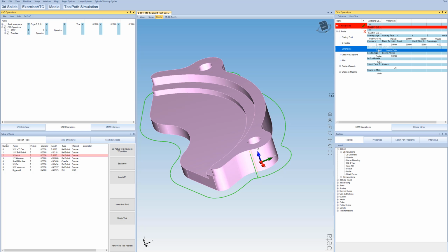So what we can do though is we have already machined the entire perimeter, so this part is kind of open, right? So what we would preferably do is select the starting chains here and just change this over to manual chain. You don't want it to automatically chain, but you just come over here and select all of these edges right here. Okay. And then refresh our toolpath. And now you can see it's going to start on the outside and work its way in. So it won't leave any sharp edges or anything like that. It's going to work a lot nicer to cut it like this. And we can do a toolpath simulation and just make sure it's doing what we expect. Okay. So that gets most of it.